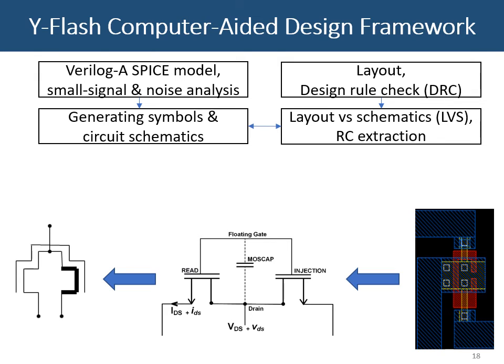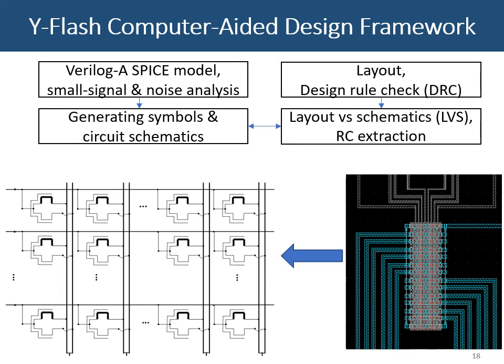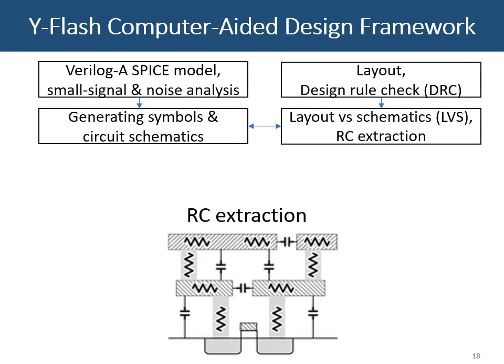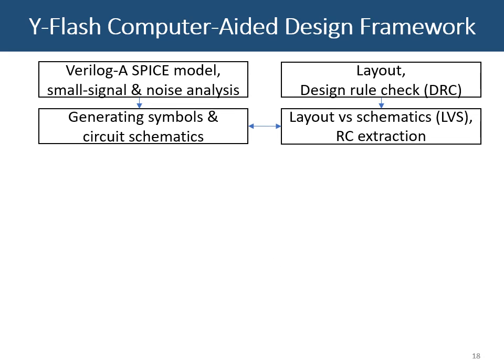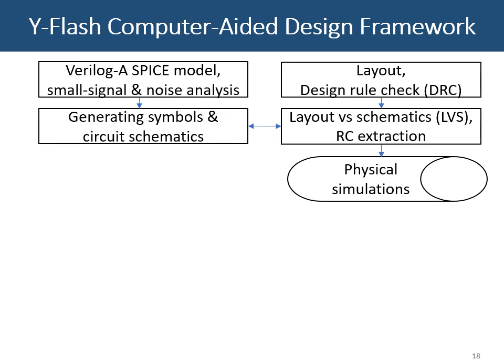The same procedure is done for a 12 by 8 Y-flash based array. Then, RC extraction is performed to extract parasitic capacitances and resistors for both the single device and the interconnect in the designed array. These steps were performed using Assura. By applying these rules appropriately during the test, we validated the design correctness, meeting the manufacturing process requirements by launching accurate post-layout simulations.